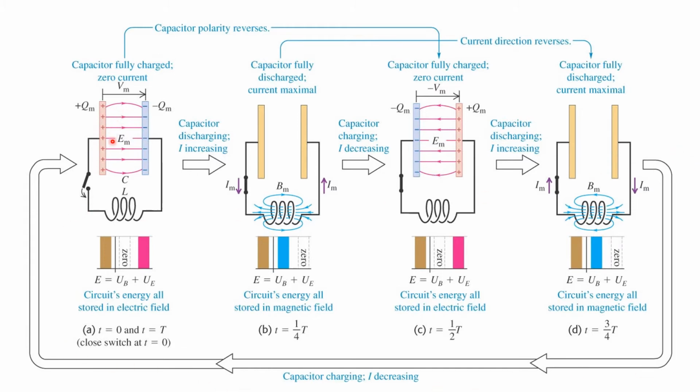So you begin with this one, the capacitor fully charged, and take note here of the polarity. This is your positive plate. You have here your negative plate. As you close the switch, your capacitor discharges through your inductor, and then this sets up the magnetic field here. Your capacitor is now again fully discharged. However, since the current persists, your capacitor will charge in the opposite polarity.